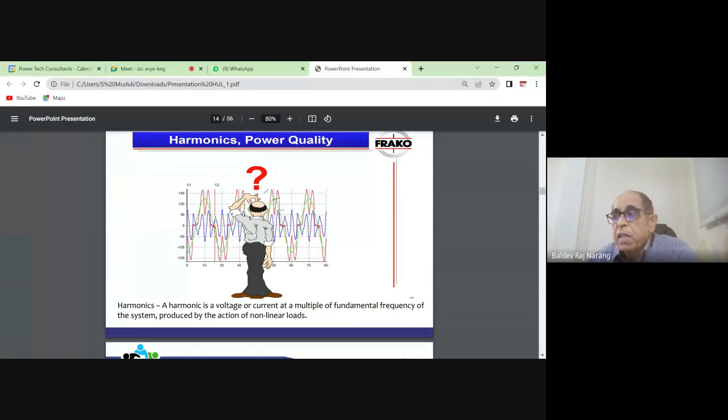Still, they are being installed, and people have gone for it in a big way. Like you see in other countries, nobody is having power factor correction. People are happy with 0.8 power factor also. They don't find the ROI impressive with putting power factor correction systems, because the active energy saved is negligible. The cost of the installation is much higher, and it doesn't justify that installation. So why are we putting in reactive power systems? For the reactive energy, and now reactive energy in India is actual energy. So that is why it is very popular here.